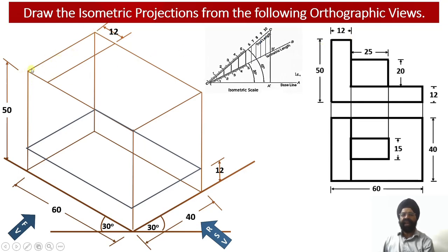So from the rear side, the thickness of the web happens to be 12 millimeter. Corresponding to this length, I have marked this dimension, and a projection line parallel to the z-axis has been drawn at the top surface of the solid. At the top surface we are going to get this rectangular projection corresponding to this vertical web, and the true shape of this horizontal rectangular web will be visible to us in the top view projections over here.